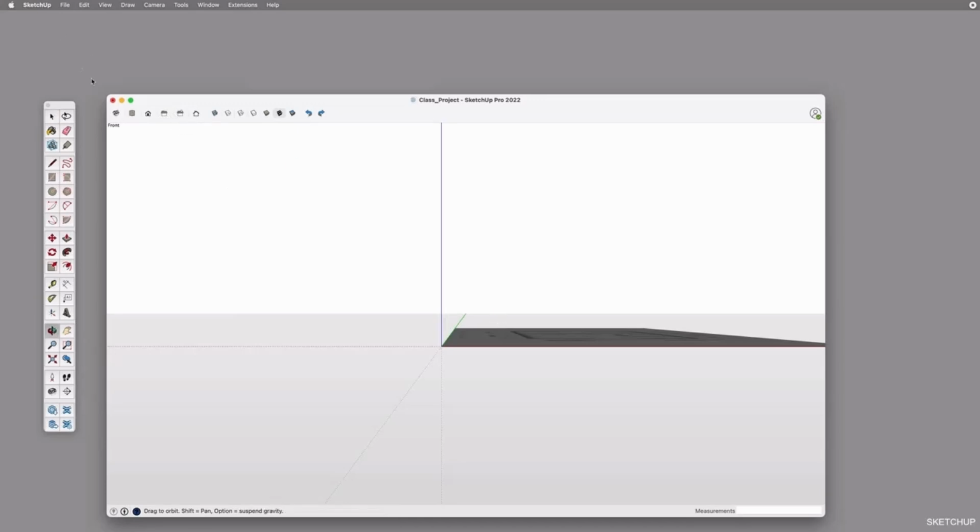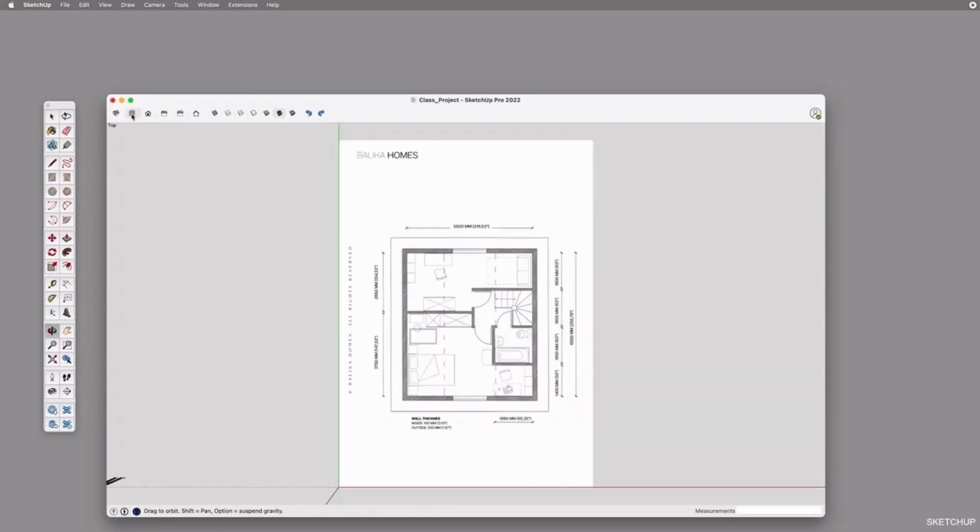We select the top view to make sure SketchUp draws our lines on the ground and not underneath or above it. Then you see another blue icon, which is called X-ray. This is a very nice preview as it lets you see your project in an X-ray version where you are able to make the surface invisible, or let's say less visible.